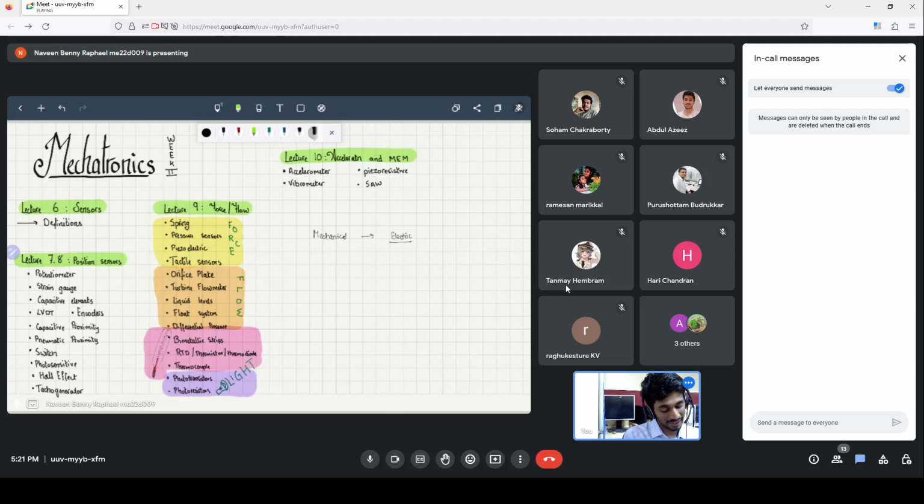The LVDT, the linearly variable differential transformer, which is quite the mouthful, is a similarly incredibly nice position sensor. And if it was not for the expense of making it, it would have been used in many more places. Potentiometers and strain gauges are unfortunately affected by temperature, but that's not the case with the LVDT, and this allows the LVDT to be used in more cases, like for example inside engines.